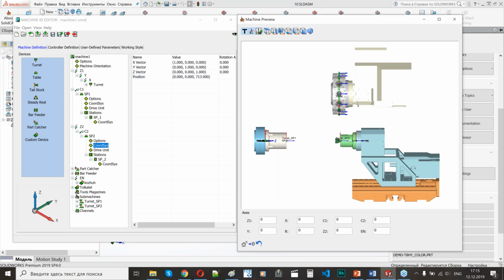You should note that the distance, with the sign, between the two spindle noses is measured on the machine, and you should do it very carefully because these figures will be used during the part transfer. So this distance should not be located on a removable device.